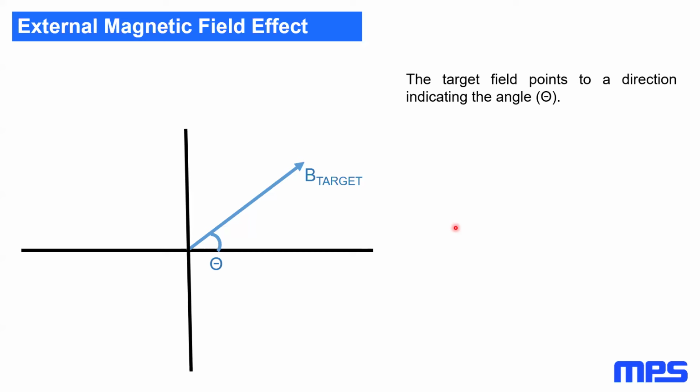It's a little more complex for position sensors because you have to get into a little bit of geometry and some trigonometry, which everybody loves, I know. So let's do that real quick. It's relatively intuitive. We're not going to do any vector math other than a quick visual vector addition. But first, we start out with a position sensor where we've got a target field. And this target field is created by your target magnet. And it's just pointing at, I don't know, about 45 degrees, something like that.